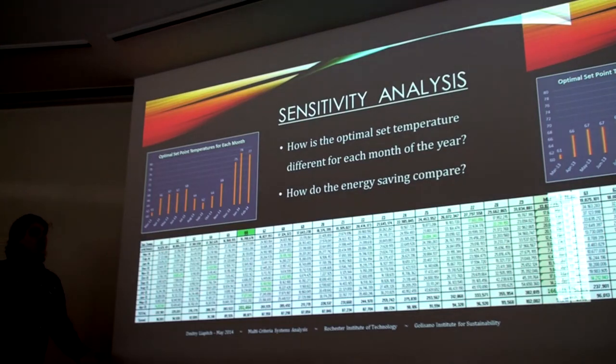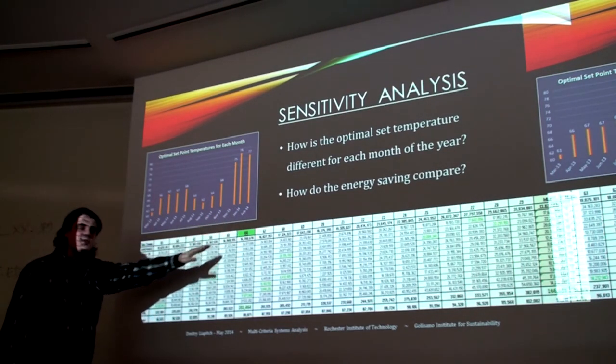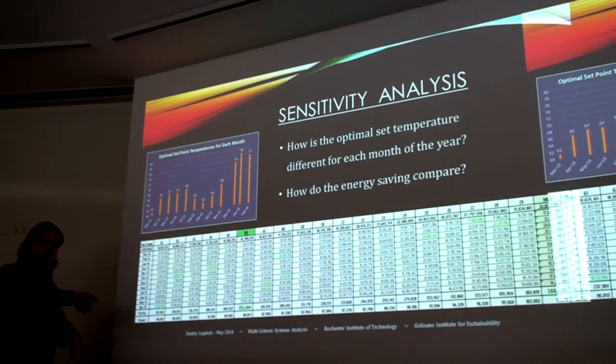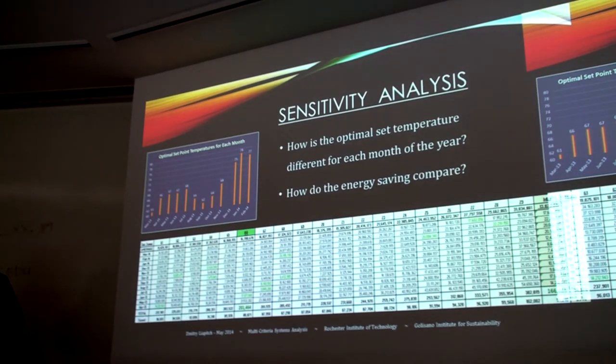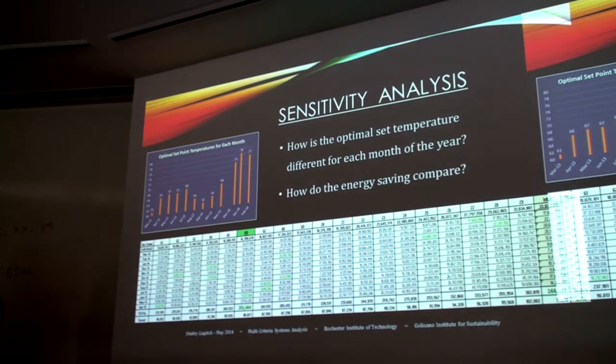The logic behind why you would want to set it at 78 degrees in January is because the air leaving the building is going to be at about 78 degrees. So it's going to be contacting that below zero temperature of air coming inside. So you really want to raise that temperature up, and in order to do that, you have to kind of go outside your normal temperatures.